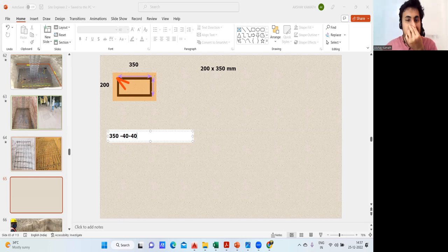Okay, so when I do this I'll reach up to here. Which point will I reach? From this outer to this outer. But usually when you find this, we have to take from center to center. That means actually your bar will be here. You will be having a rebar here like this. These bars will be there. Only then it will look like a column, no?